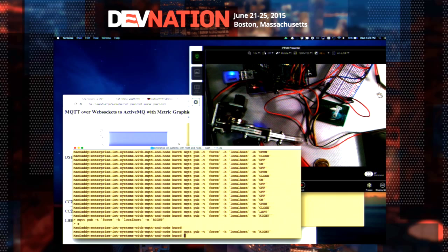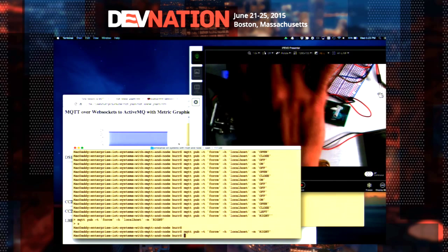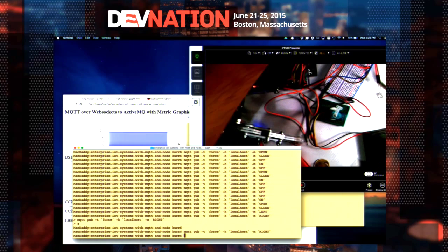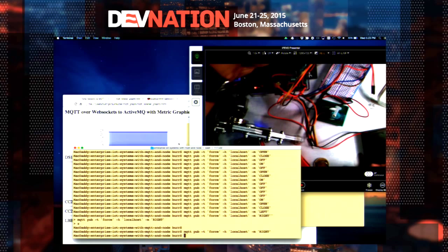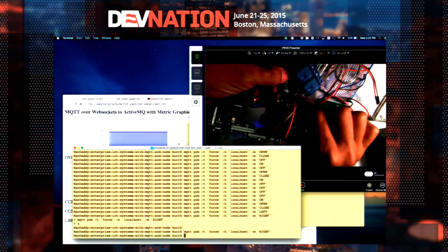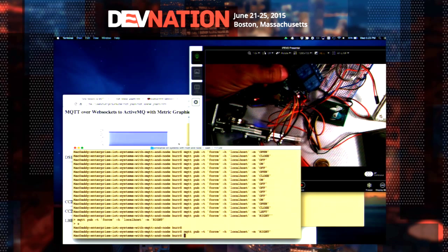And in the case of a lamp, a higher voltage thing, this is basically a 5-volt device. An Arduino's 5-volt, this is technically 3.3, but you can also use 5 with it. The higher voltage device, I'm going to pull my relay into the view here, see a little bit. So basically, you can use the little low voltage intelligent Linux machine. Using a relay, you can drive a high voltage device.